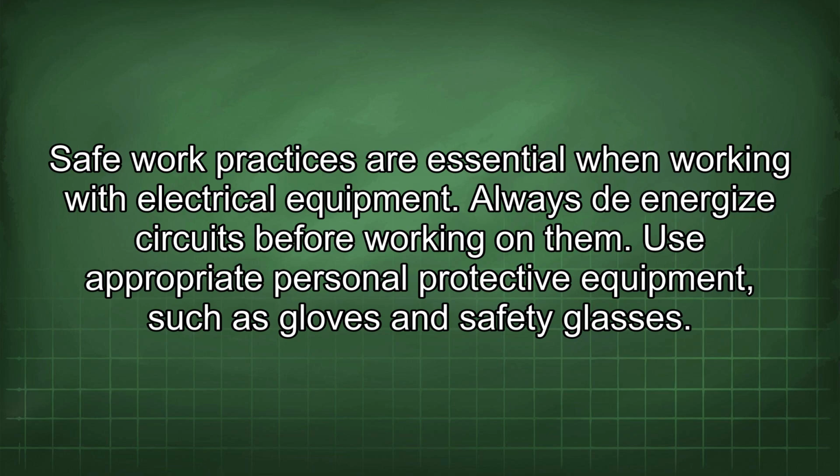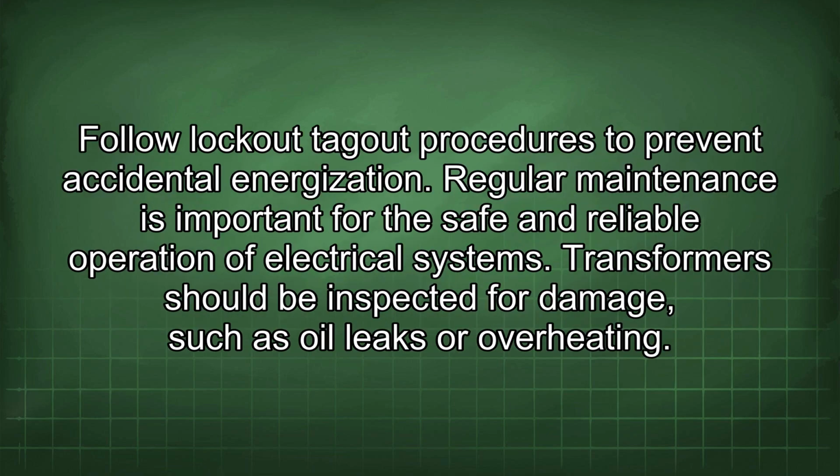Always de-energize circuits before working on them. Use appropriate personal protective equipment, such as gloves and safety glasses. Follow lockout-tagout procedures to prevent accidental energization.